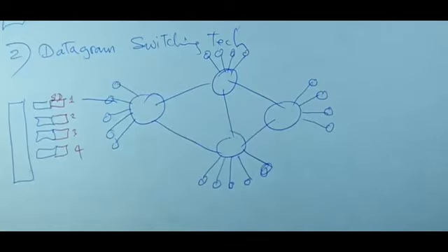It's a multi-point technique. It's like broadcasting. You just broadcast to everybody, and only the intended party takes the message. This is not good either. This has a few little problems, and you should know these things. I'm just refreshing your information. If you are broadcasting, then if I'm transmitting and you want to transmit, you have to wait until I'm finished. And then if someone else wants to transmit after that, they have to wait for me to finish and you to finish. So the problem with broadcasting is the delay.